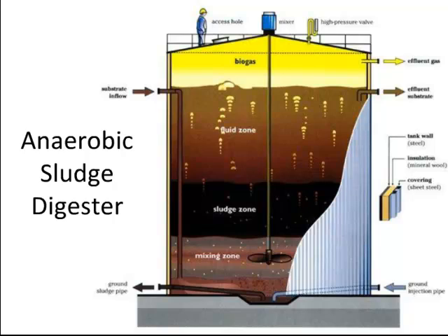then that can be applied as a fertilizer. Now the key thing there is it's put very thin, because this sludge can still contain pathogens, and you need to destroy the pathogens before it can go into contact with any human. So a great way of destroying pathogens is sunlight. So by putting it in these very thin drying beds, it exposes it to large amounts of sunlight, to ultraviolet light, while it's drying up, and will render it usable.